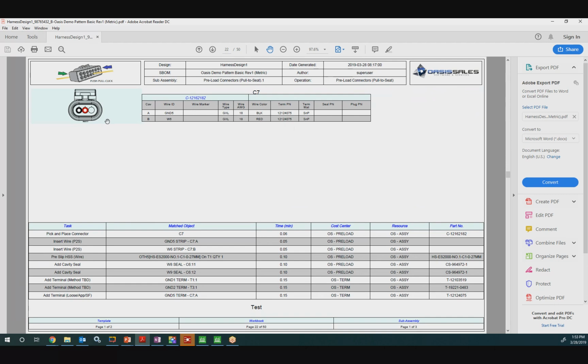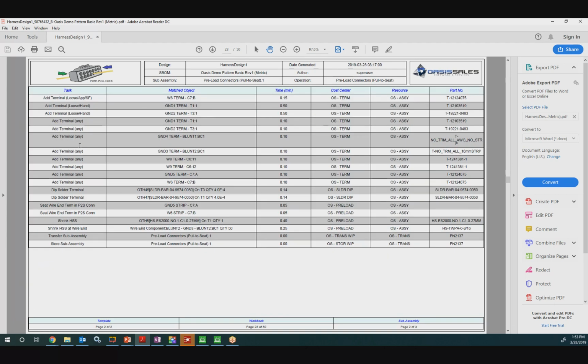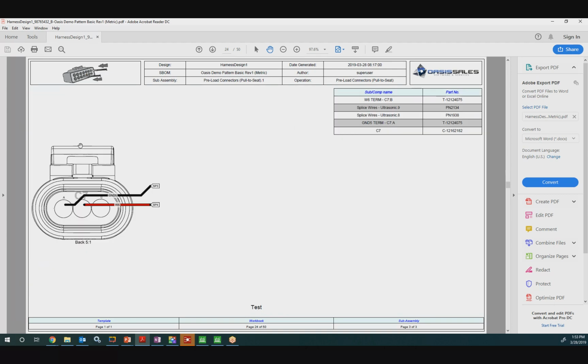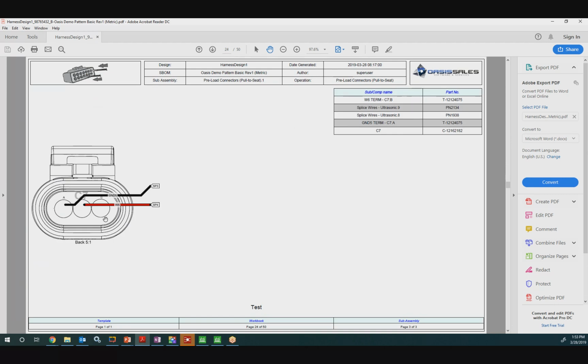Say, for example, if they thought that the cavity arrangement went from A, B, and C from left to right, but they insert the wires thinking that it goes from right to left. Again, different formats. These are different providers that are being used to show the insertion of the wires into the connector. So in here, obviously, we colored in the cavities. And in this one, we're identifying the wire going into the cavity as well as where the other end of that wire will be at.